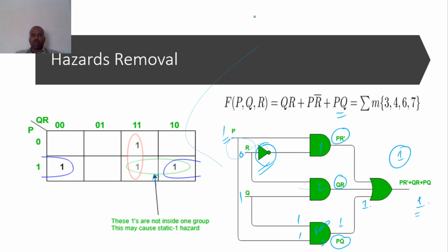So there are two ways. One is reduce the delay, and second one is add extra components. These are the two methods to reduce these hazards. So this is the example for static hazard. So I hope you guys understand. Next we'll move to dynamic hazard. So first dynamic hazard, as already I have explained more. It is AND gate 1 1, output should be 1.